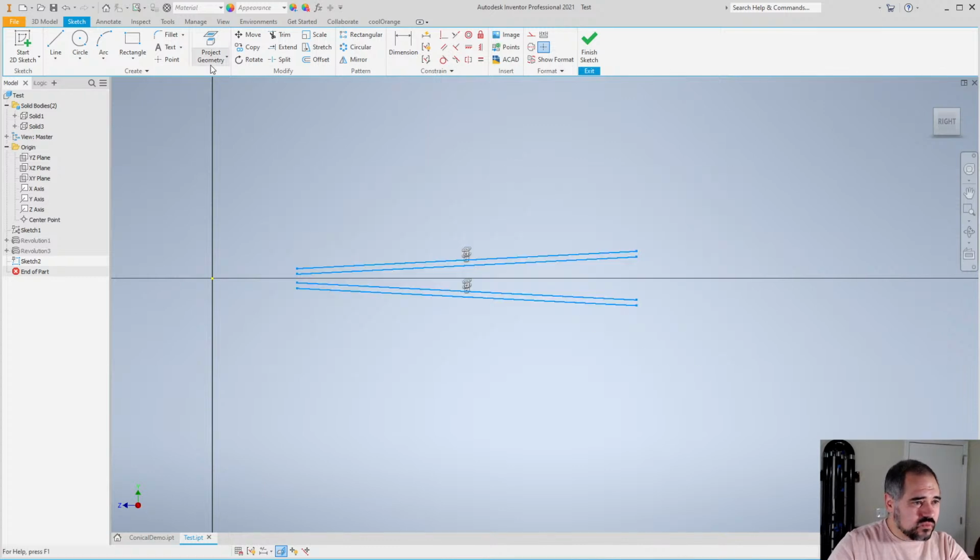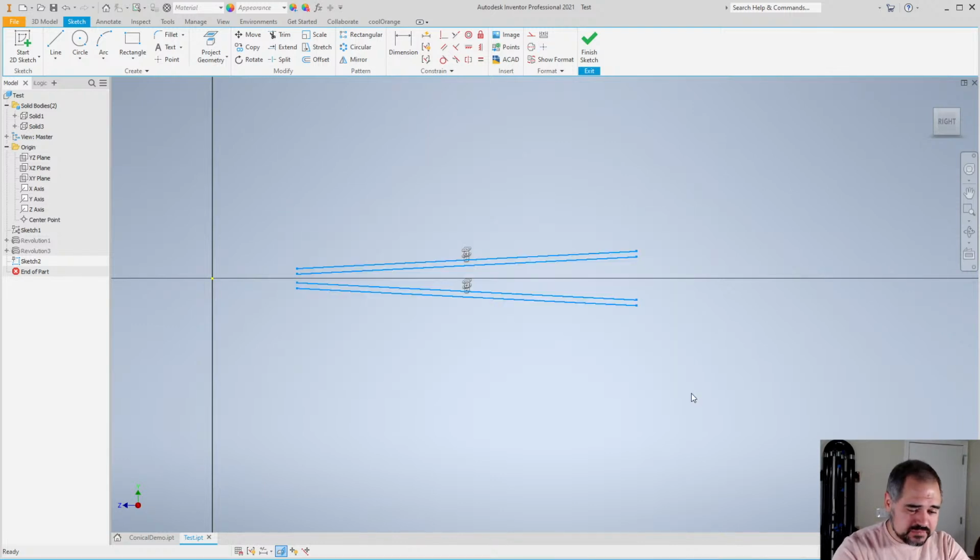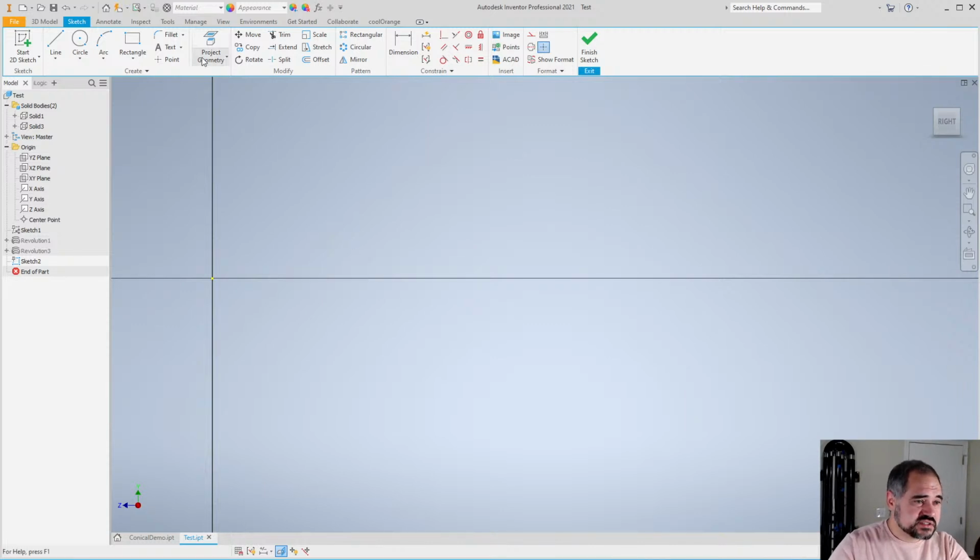Personally, though, whenever you have these projected geometries and then try to go back and change or update things after the fact, there's a lot of stuff that can go wrong, and you end up with files that need a lot of babysitting whenever you need to change something, or at least that's my experience. So I'm actually not going to define anything using the solids that already exist.